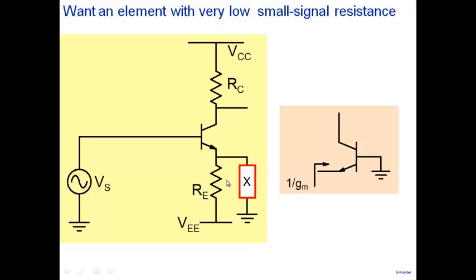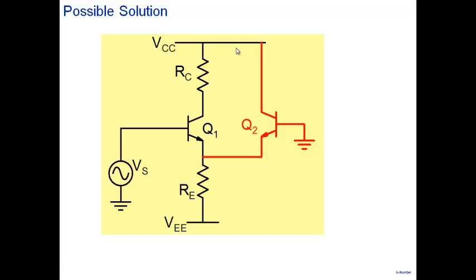Okay, and let's do that. So we are going to take this particular node and connect it to the emitter, and base we will ground, and collector we have to bias in forward active mode. So collector we can connect back to VCC. So let's do that. Okay, so we've connected it here, Q2, and the transistor is a three terminal device, so we connect it to VCC here. And signal of course is being applied here. We'll come to the DC bias in a moment.